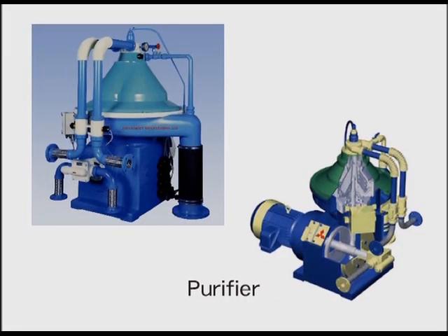First, I will explain the typical cleaning procedure for lube oil system in the vessel. Select the purifier based on gravity disc selection procedure described in the Operation Manual of Purifier. The appropriate interval for discharging the sludge varies with the quantity of the mixed-in insoluble content, so adjust the interval for discharging after having checked the degree of dirt of the bowl.